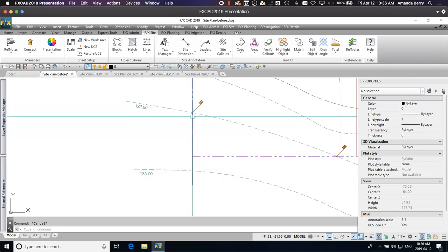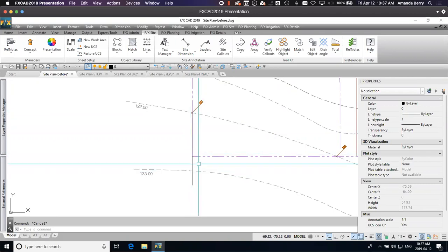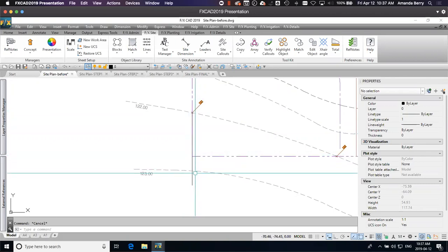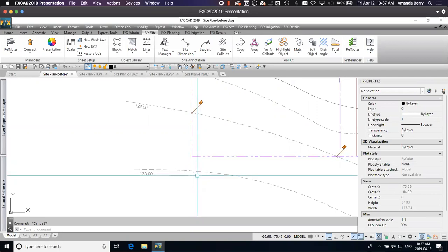So a straight line through here. I'd figure out the slope between those two, and then I'd figure out the run over here in order to determine, switch the calculation over again, and to determine the drop between the 123 elevation I know here and this point right here. So I know the distance between these 2 points, and I just need to figure out the slope in order to figure out the drop or the fall or the rise.